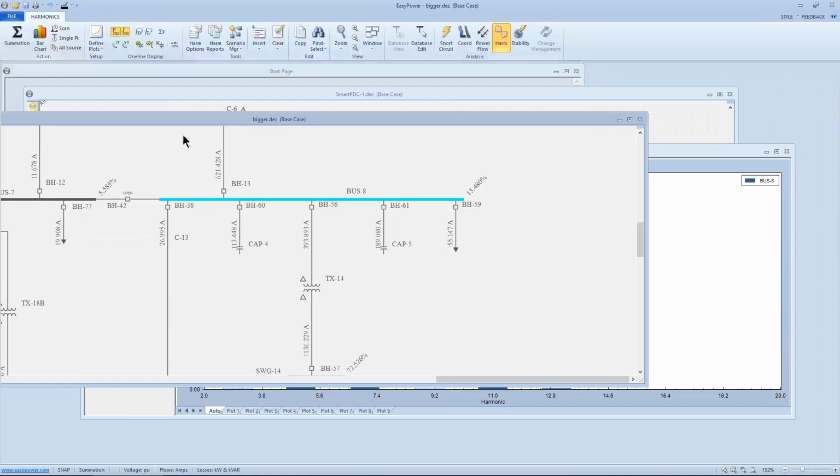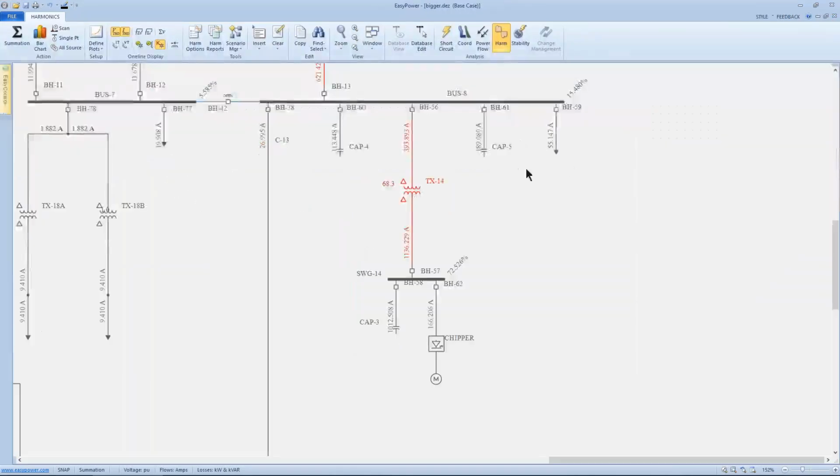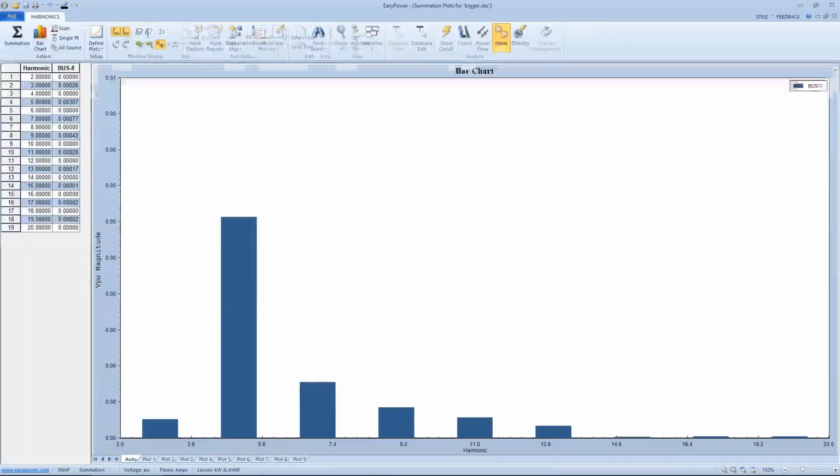Likewise, there's the potential for that extra harmonic content to cause a problem in transformers if they haven't been properly sized or derated. The tool shows us, on the top row up here, the K factor that's suggested for my transformers in this particular system, and I can see the K factor here is 68.3, which is huge compared to what it was before we had this motor in there.